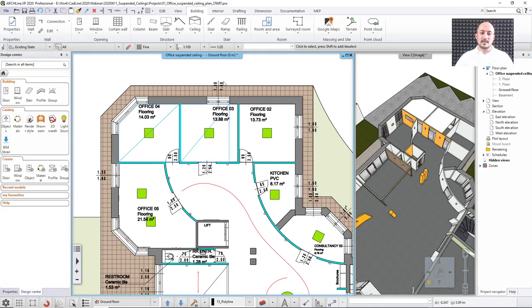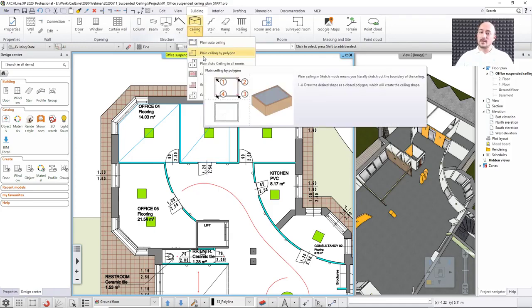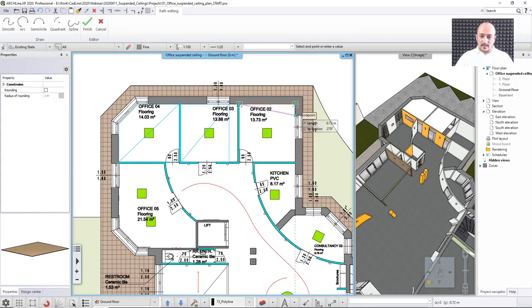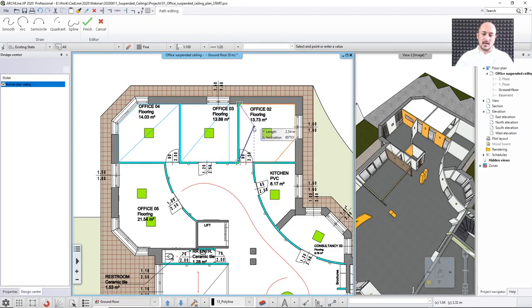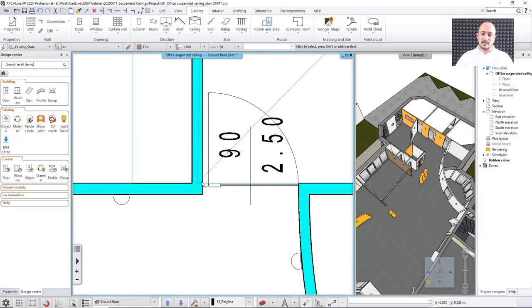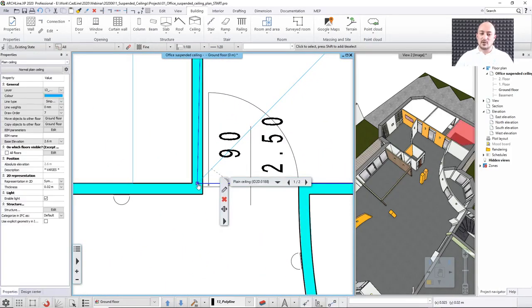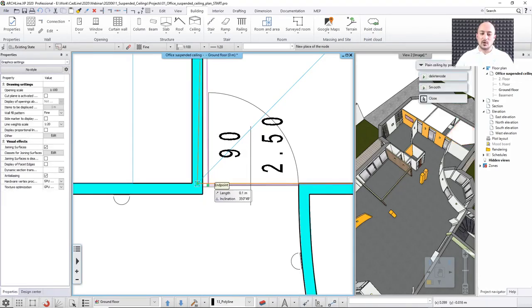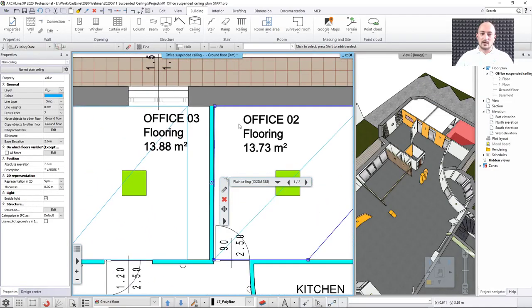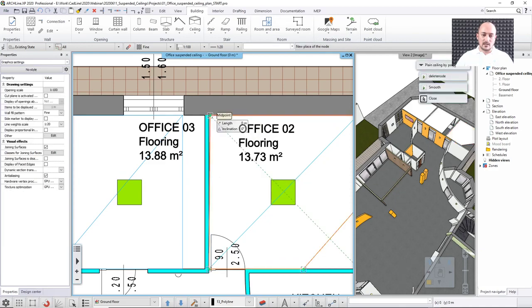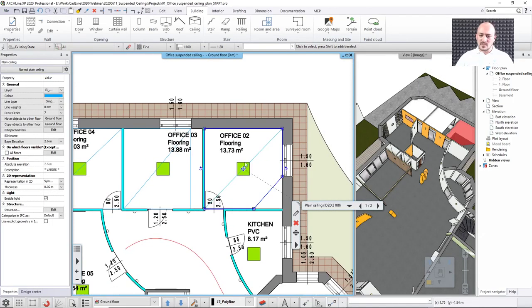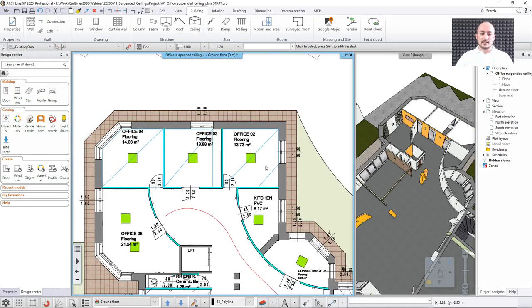Now the same thing applies, just as I mentioned, even if you create it with the polygon. So in that case, you just click here, and you can just, I don't know, for example, skip this part and then just do it like that. And for example, if I make a mistake, I just clicked here inside the room, the same way you can fix it. You just click here, click on move node, fix the position, and then there you go. You already have the proper room. And actually, I need to fix this as well. Okay, so it should be over there. So the same way you can just easily fix that item in front of you in the 2D, and of course in the 3D as well.